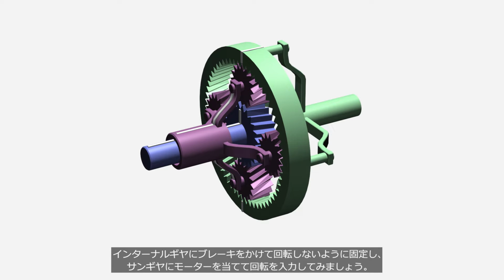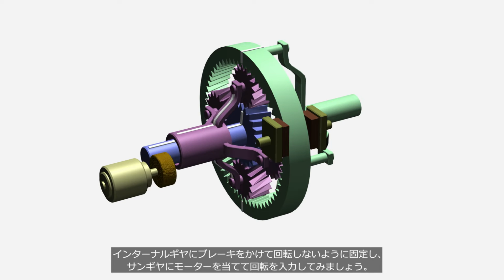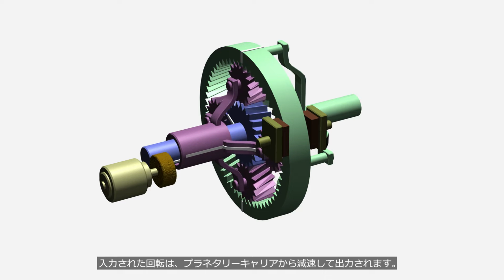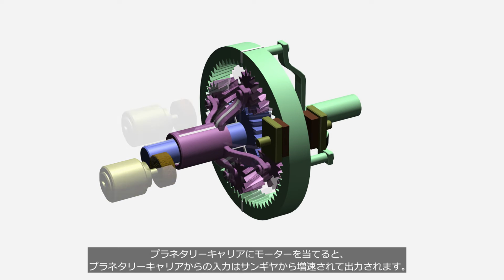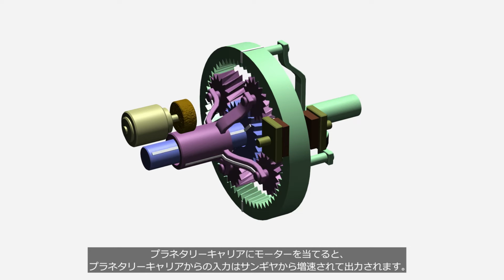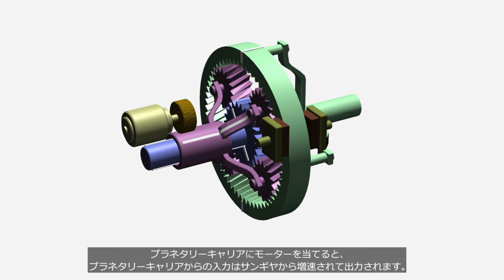Let's try applying the brake to the internal gear to prevent it from rotating, and applying an electric motor to the sun gear shaft for input rotation. The input rotation speed into the sun gear is reduced, and then output from the planetary carrier. When the electric motor is applied to the planetary carrier, the input rotation speed into the planetary carrier is increased, and then output from the sun gear.